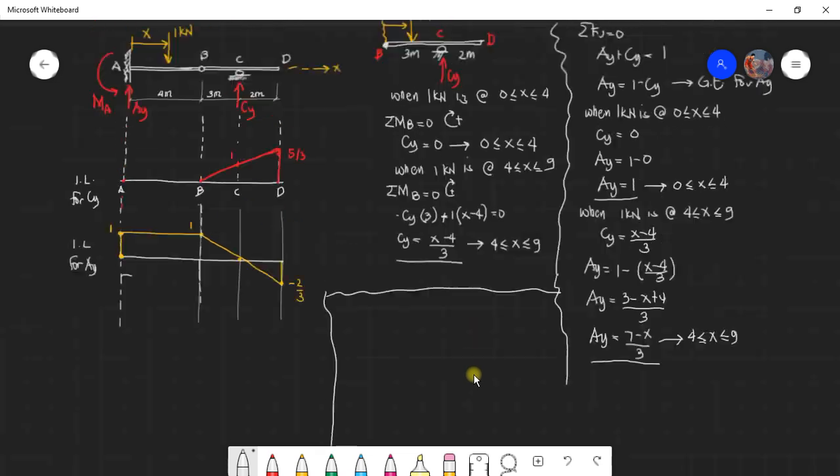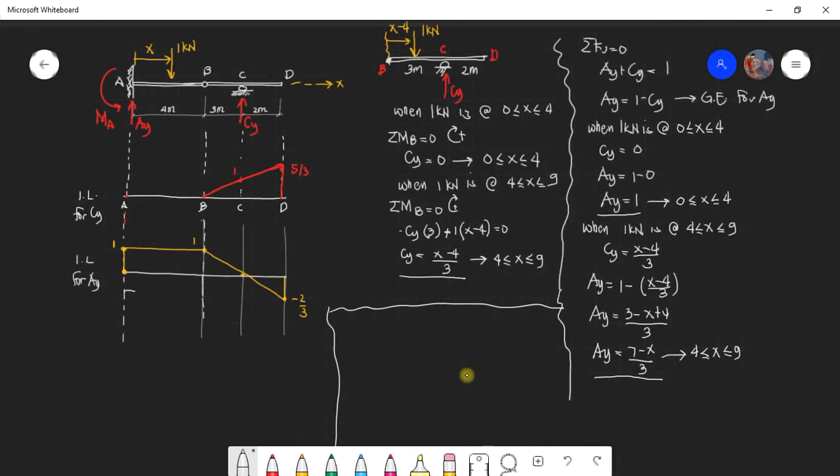Okay, so using the whole equation, we'll take moment or whole structure, we'll take moment at A equal to 0. Okay? So, let's say clockwise positive. So, we have negative MA. Okay, negative MA. Okay, plus yung 1 kilonewton times X. And then minus CY.